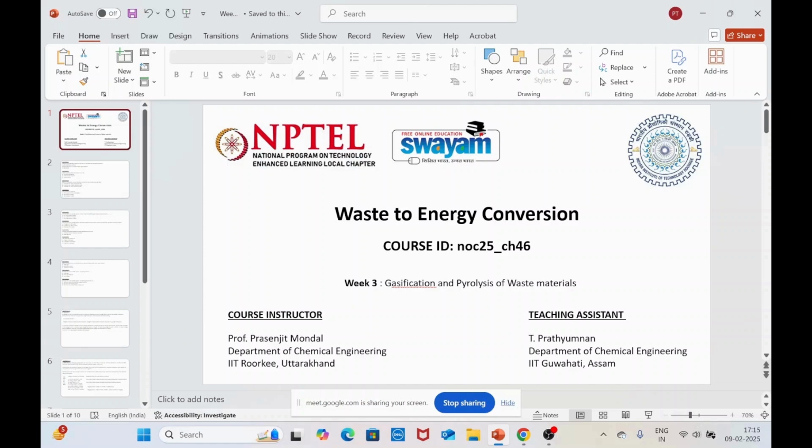In incineration, you have uncontrolled or excess supply of air. Again, we had the classification based on the R value, which is nothing but the oxygen to fuel or waste material ratio: greater than 2.5, 0.68 to 2.5, and less than 0.68.